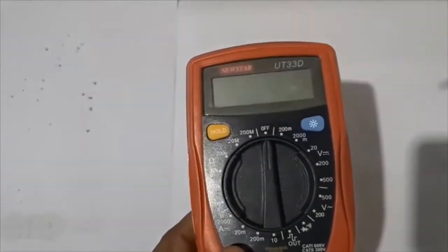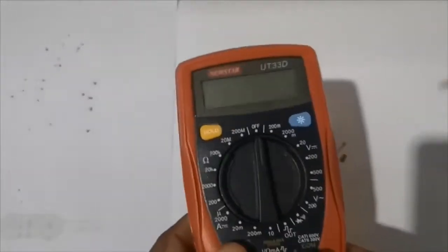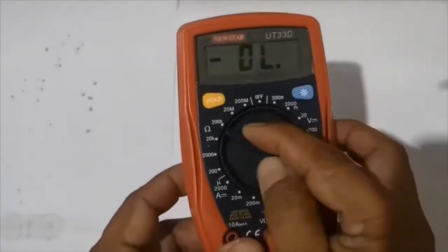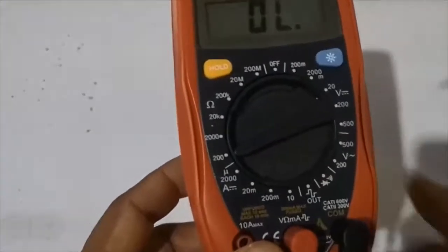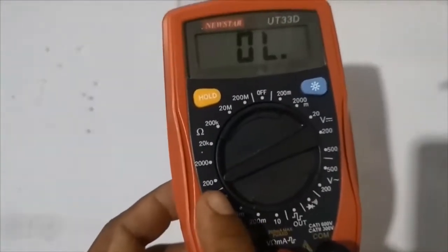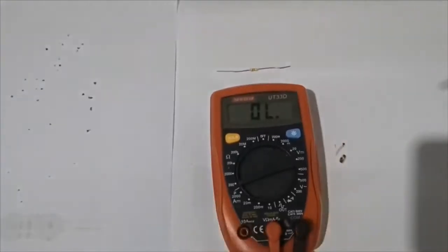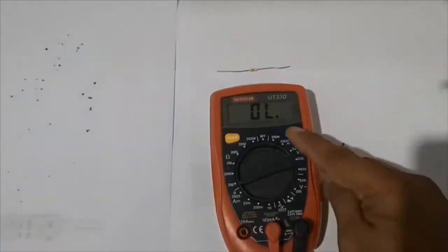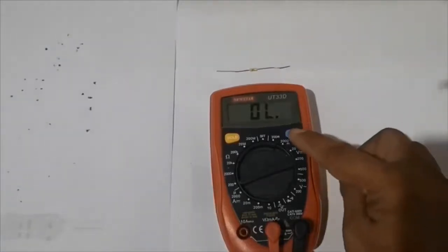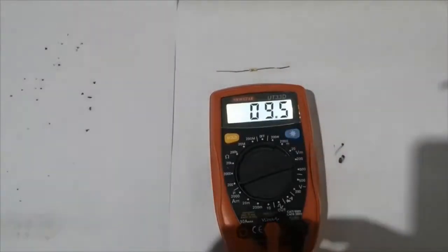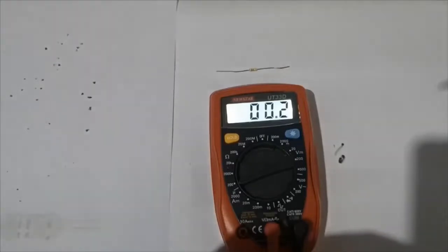Now I am going to show you how to measure the resistance using the digital multimeter. So this is the digital multimeter. First, I will set the range to 200. There, as you can see, it is now set to 200. Then I will turn on the illumination knob so that the screen will be seen clearly. There you can see it displayed OL, that means infinite. Then we short the test leads and it reads 0.1, which is almost equivalent to 0.